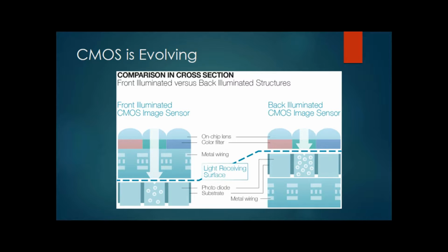So obviously this is a pretty expensive technology, and they put a lot of money into getting this all to work. And they've used this to go after the cell phone market, which means itsy bitsy teeny bitty little chips that have like 1 or 2 micron pixels. Not very well suited to astronomy, where you might have a 2,000 millimeter focal length. You want to have like a 9 micron pixel, or maybe at least a 6 micron pixel to use on a C8. And a bigger telescope might require even bigger pixels. So the current generation of chips aren't suitable for use in astronomy, even though they have performance that's much closer to CCD.